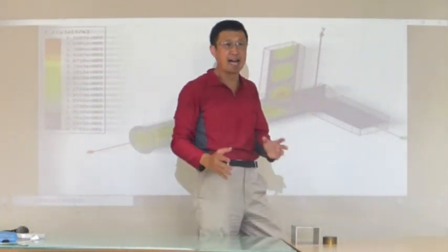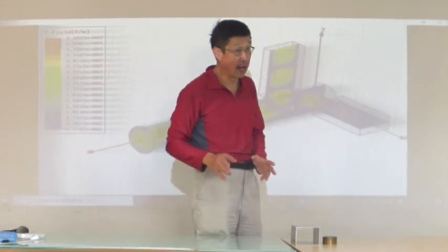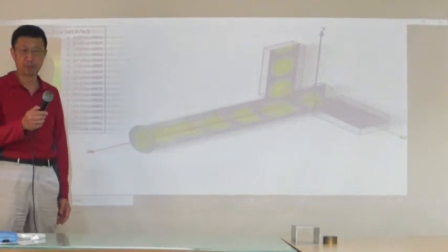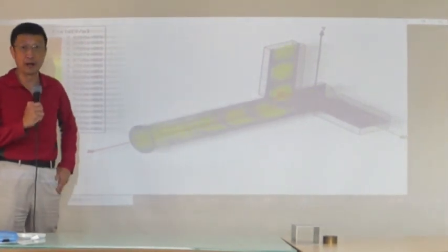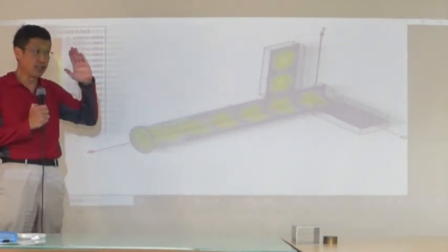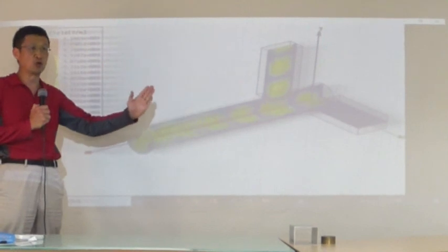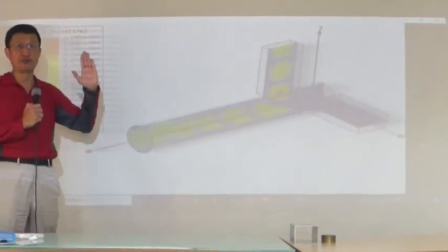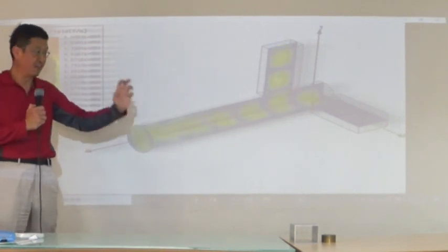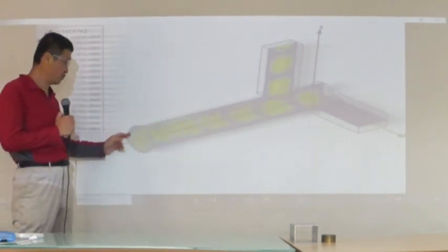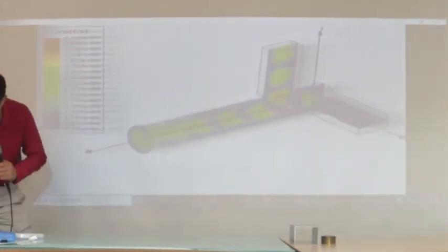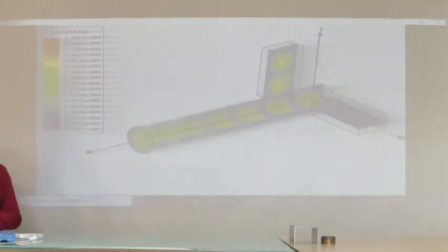So just like optics, they use the same idea. For example, a quarter wave plate. The purpose is to generate something like this one. The incident wave is divided into two parts. And because Kz is different, we can change the phase. And eventually we can synthesize a circularly polarized wave or a linearly polarized wave, a right-hand or a left-hand circularly polarized wave.